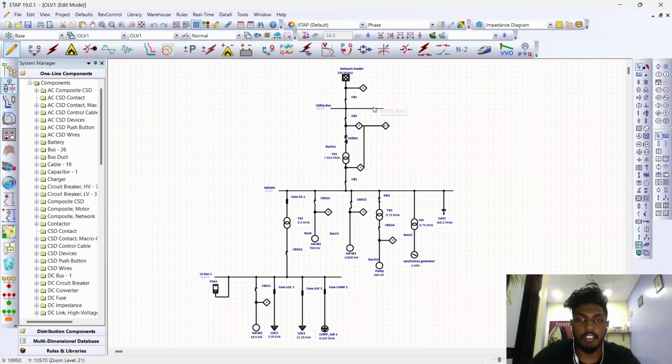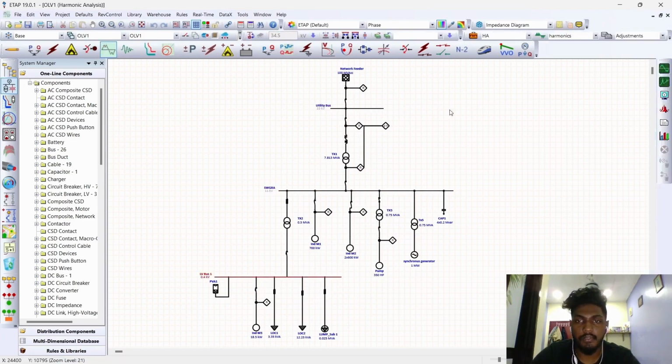So these are the buses I mentioned earlier for the harmonic distortion, and for the harmonic distortion we have to run harmonic load flow first. After we run the load flow, we can go straight to the graph. I want to explain in more detail about the graph.